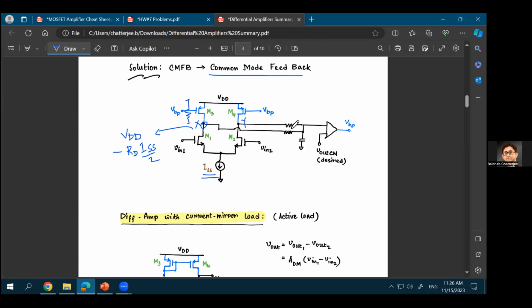Now, what you're doing here is taking an average of those two DC bias points, and averaging is in some way low-pass filtering. In terms of digital, if you want to take two values X and Y and take the average, you take X plus Y and divide it by 2.